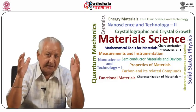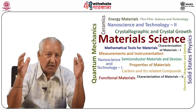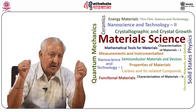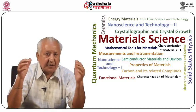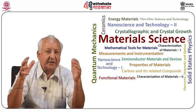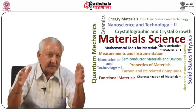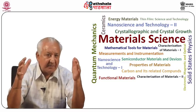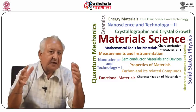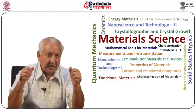Growth from the molten phase is the best method for growing large crystals of high perfection faster than any other method. Melt growth normally requires that the material melts congruently, in the sense that it does not decompose below or near the melting point, and has a manageable vapor pressure at its melting point. Melt growth may be divided into four main groups of techniques.